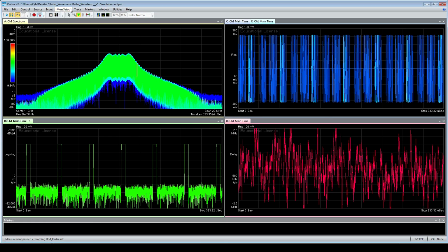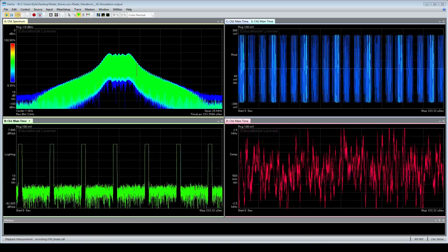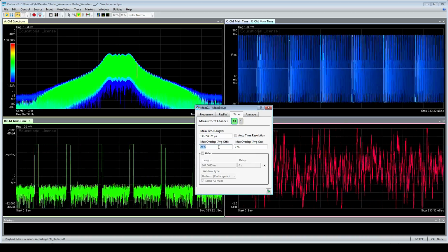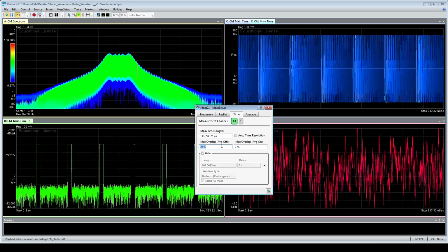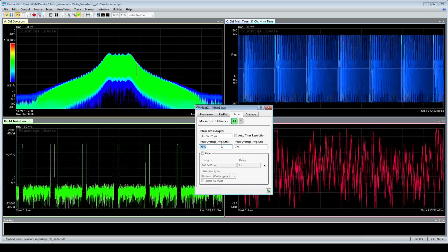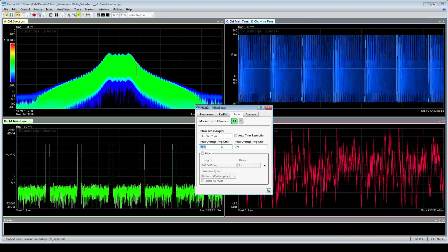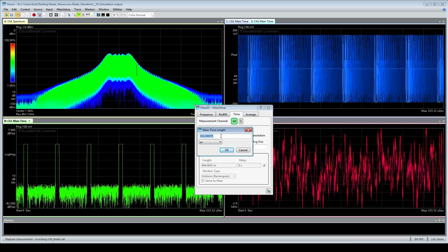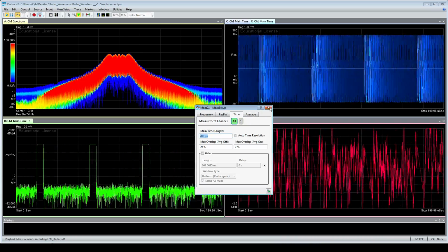So back to what we were talking about with the time. It was running relatively fast, and if I press play, you see that it's visually hard to see what's going on. If I change this from 90 to 99, we've slowed it down drastically. What we're doing here is changing the amount of information that the analyzer is taking in and throwing out every time it's analyzing the spectrum. We've gone from throwing out 10% and taking in 10% to throwing out 1% and taking in 1%. And if we want to, we can also reduce the time spectrum, the amount of time we're examining in any interval.